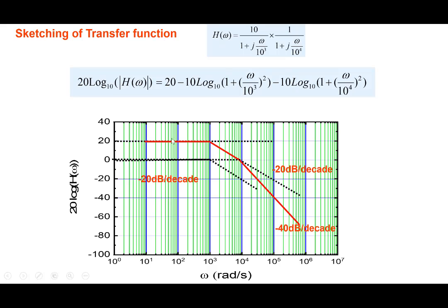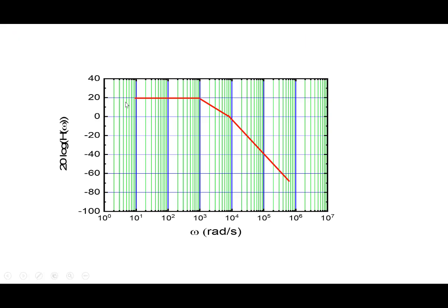That's how we sketch it out, as I said. So the transfer function that we have sketched is accurate over most of the places except close to the corner points here. At that corner point, this one is an approximate curve. If we want an exact value, of course, at that particular point, we can go in and substitute and get the exact value also at that particular place here, right? So this is the approximate variation of the transfer function with frequency that we see here.